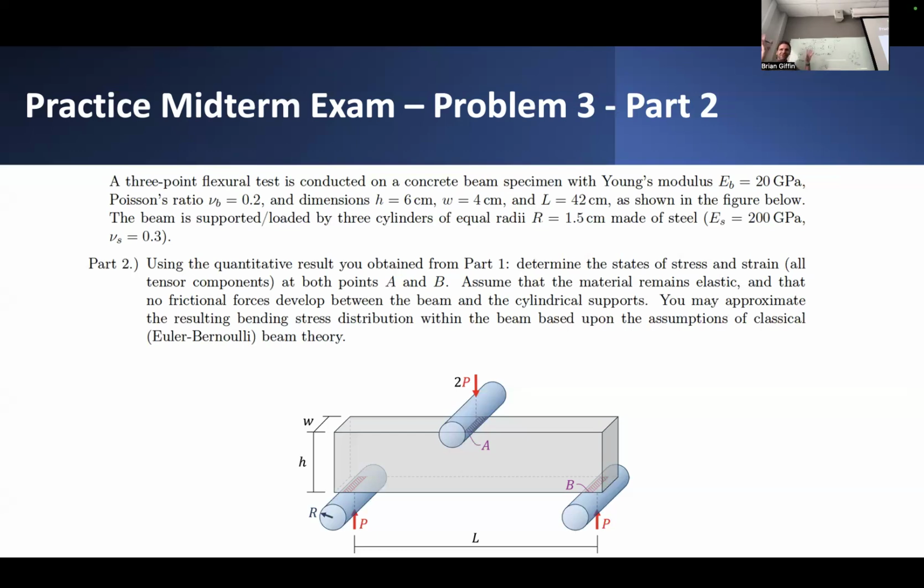I encourage you to go back, review this, and maybe refresh your memory on shear and bending moment diagrams. It still applies here. But the linear variation of xx stress, assuming this classical beam bending stress distribution that varies linearly with height y above the neutral axis, is simply My over I, right?